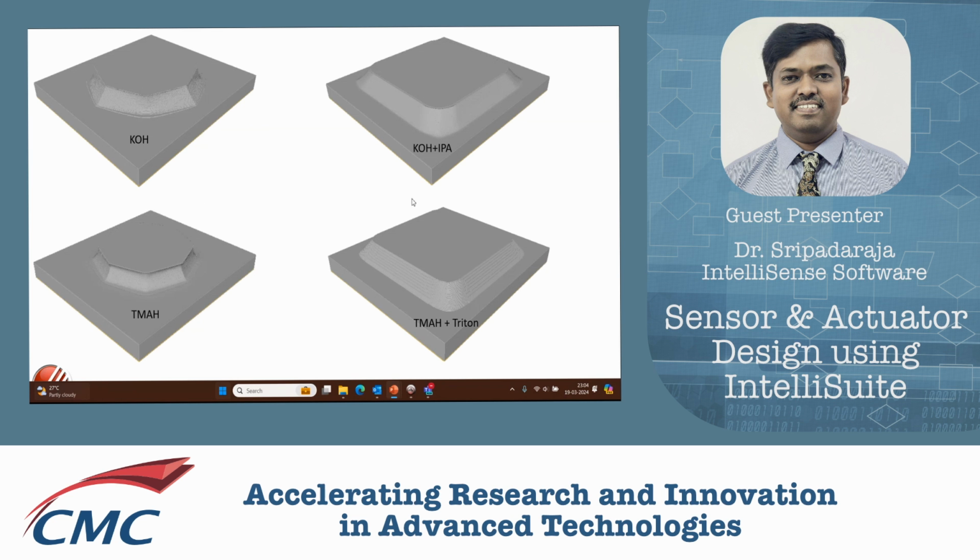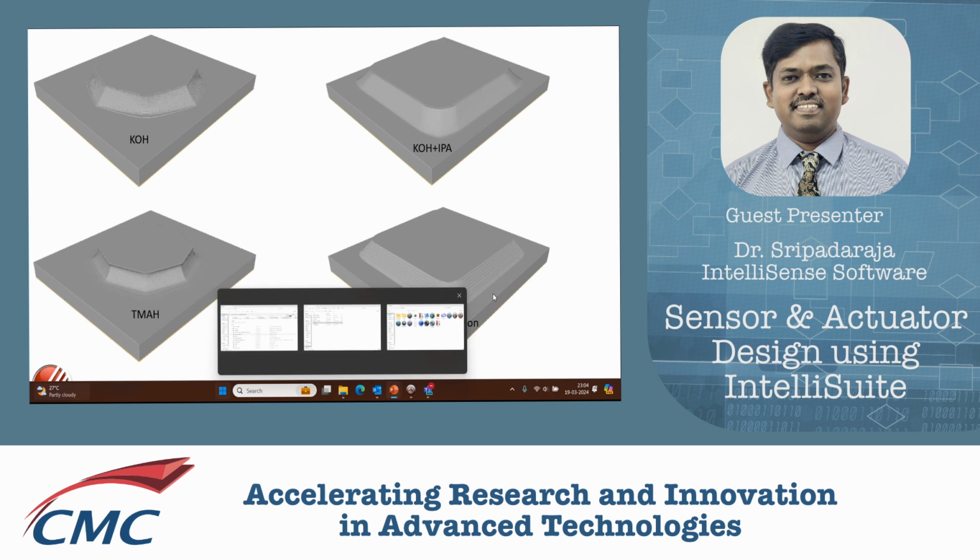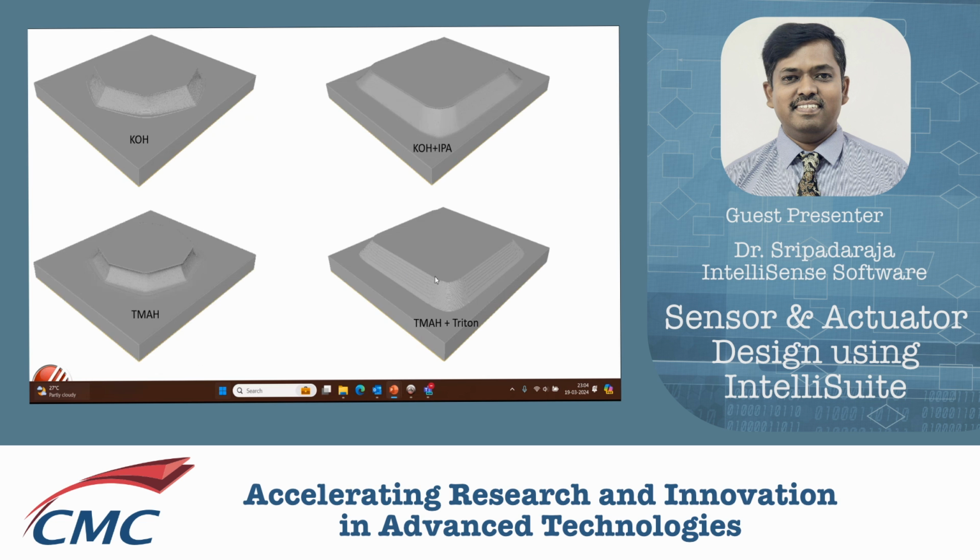So this is an example where we see KOH etching, KOH plus IPA, TMAH, and TMAH Triton. So what are these basically? This is the surface profile that is achieved with a square shape mask. When it's with IPA, this is the profile. With Triton, this is the profile. With the Triton and TMAH combination, this is the profile that we have.